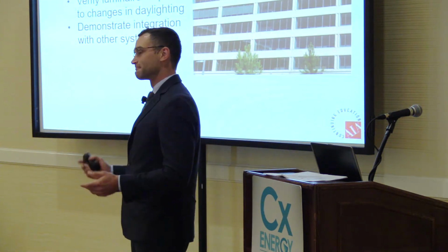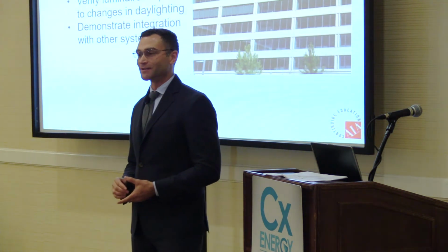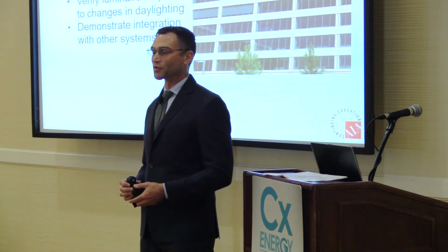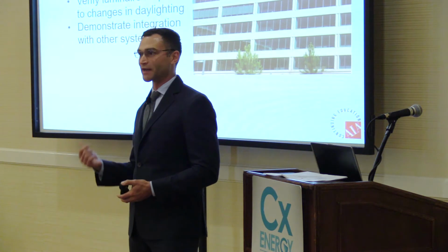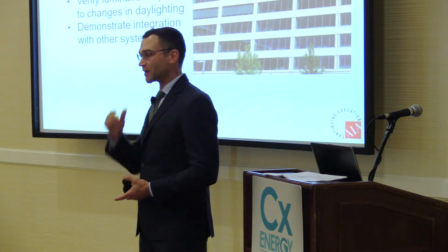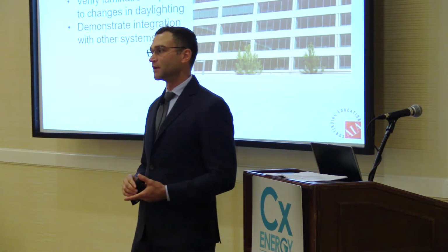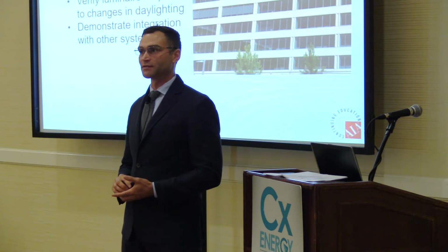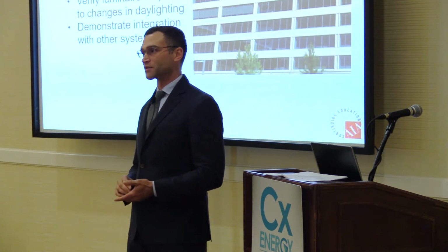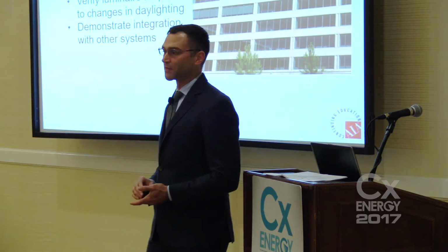So how do you test a daylight harvesting system? That really could begin during the pre-design. You need to know what the lighting level's set at, any dead band, any type of user information. And I alluded to before, if you show up without that information, what do you do? You certainly can still test it, and you can document how it's installed. And that's a lot better than nothing.